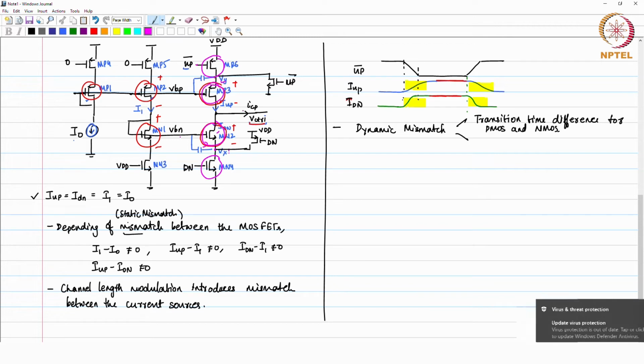Also the control voltage may need to vary across the frequency range which you need for your PLL. So, if your oscillator goes from x frequency to 2x frequency, control voltage may vary by 2x. So, if control voltage changes, in that case also your output current will change.